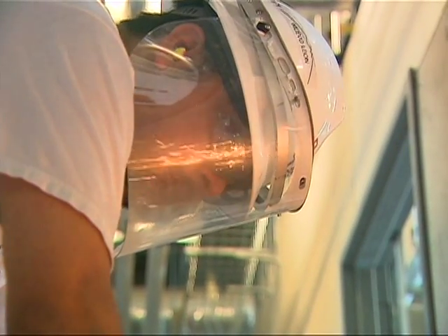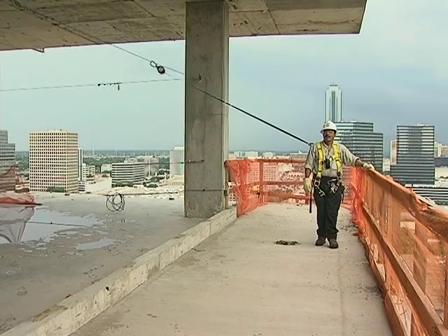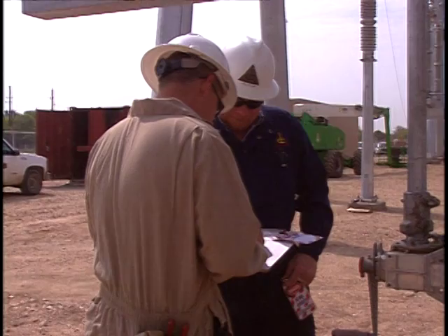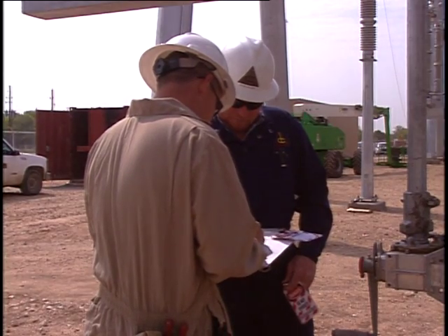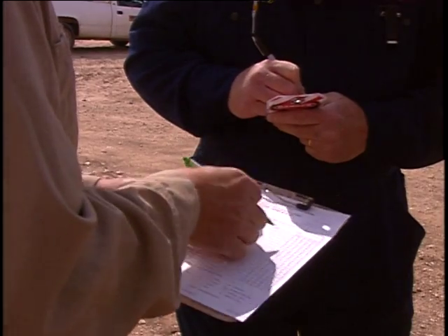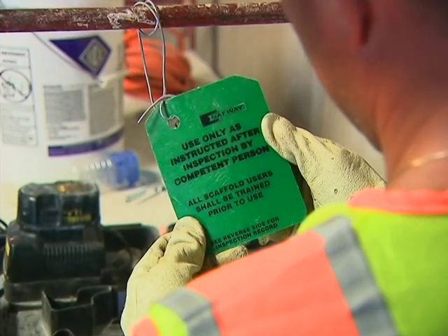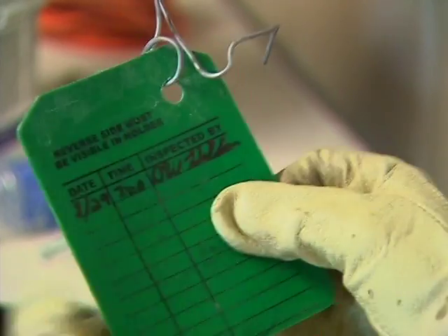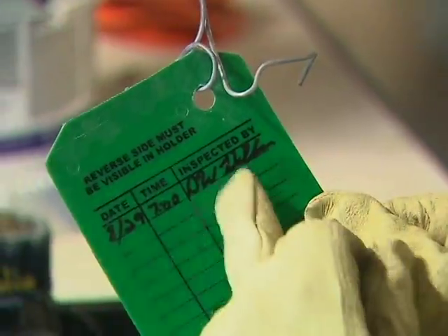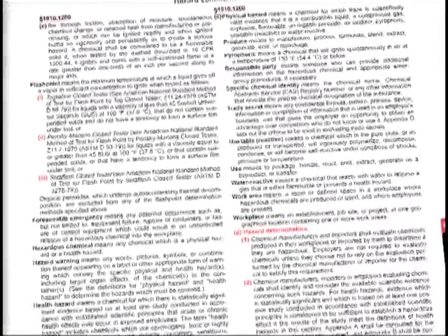Personal protective equipment is designed to protect employees from workplace hazards that can cause injury or illness. OSHA requires the employer to implement a written hazard assessment program. Written certification of the hazard assessment should identify the workplace evaluated, the person certifying that the assessment has been performed, and dates of the hazard assessment. OSHA Regulation 29 CFR 1910.